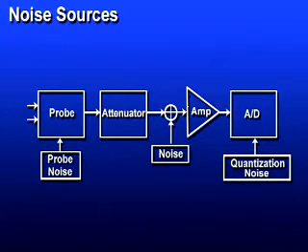So far, all the measurements and results we looked at were with the scope in its most sensitive range. So we were just looking at the native noise of the amplifier input stage of the scope. Now when you go to less sensitive ranges, the scope inserts an attenuator in here so that the scope can get the correct scaling for larger amplitude signals at the front panel BNC connector. So if you insert an attenuator, let's say a 10-to-1 attenuator, the scope will think that this 400 microvolts noise here is actually 4 millivolts noise here, referenced to the input BNC.